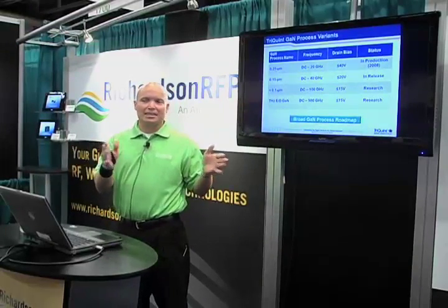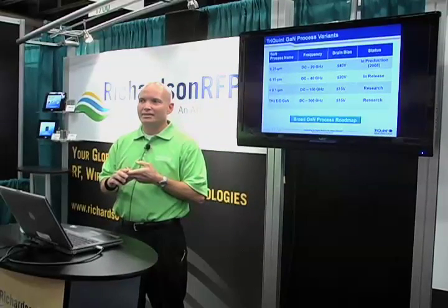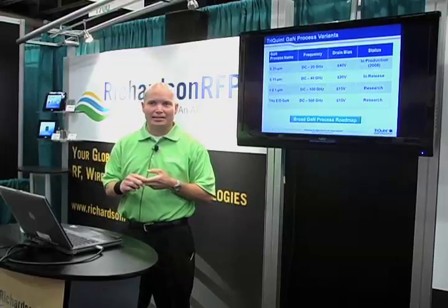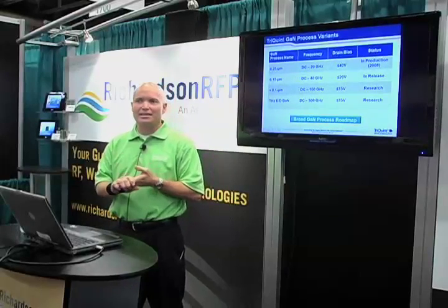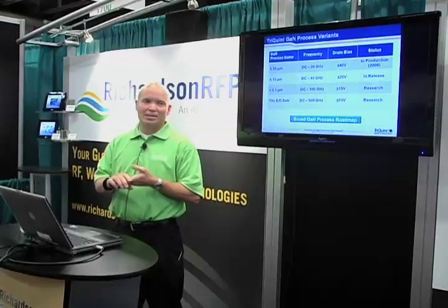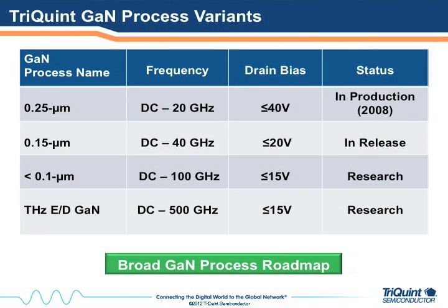We're supporting the same 6 gigahertz and below products with our quarter-micron process. That gives you the higher efficiency, higher gain than the competing half-micron technologies. But it also allows the customer base to achieve world-class performance up through X-band as well as Ku band using the quarter-micron. To attack the Ka band market, we're developing a 0.15 micron technology.